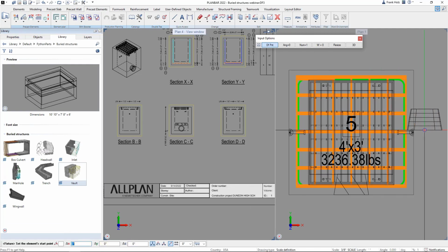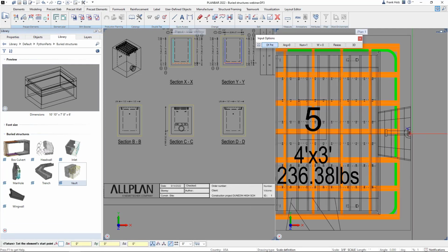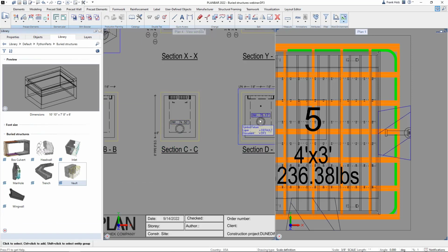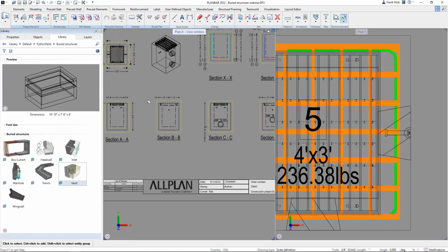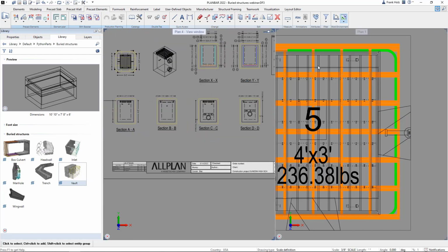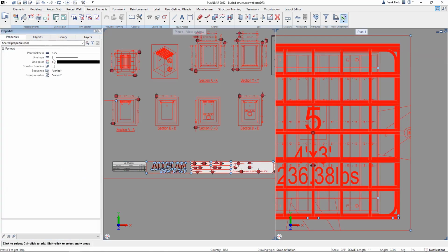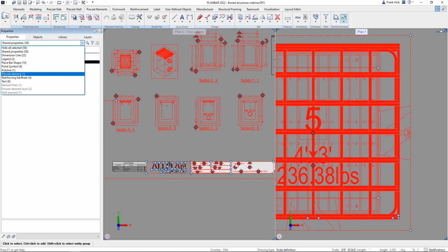I'll go ahead and place just one more here. Show you how easy it is to first rotate it into position, and now I'm going to do this 1 foot up. And so now we've placed that. We can see the inverts. We got 74 and a half, 75, 1/7, so 2 inches here. And remember, it's coming off of that 78. So if the top of this one changes, or perhaps I just make a copy for the next one in our project, and I want to change it to right down the street, it's maybe say 80 foot up.